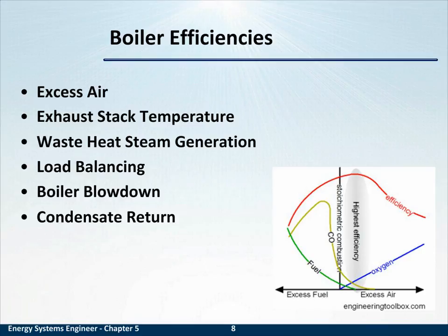Boiler blowdown: as you continue to evaporate water through steam, you evaporate pure water. Much like in the cooling tower, you evaporate pure water. What's left is water that has more hardness, more corrosion-causing elements in it. And so you use your boiler blowdown, just like your cooling tower blowdown, to remove that most concentrated water in the boiler.